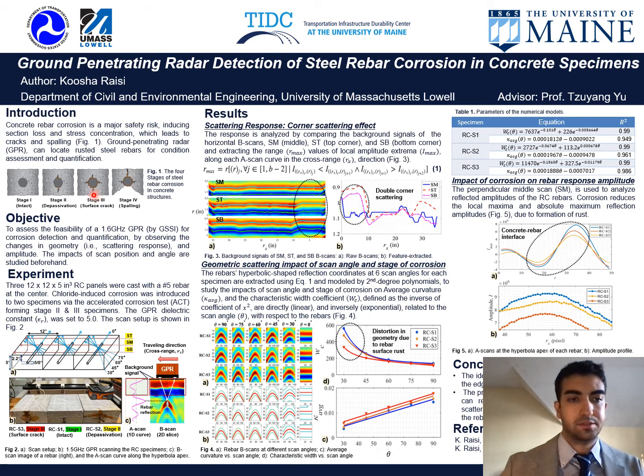And we have initiation of cracks, and at stage 3, the cracks have advanced to the surface, so we can basically see the cracks. And the last stage, which is the spalling, we can see that the concrete specimen or infrastructure is opened, and we can see the reinforcement. We call that spalling. And the specimen is hopeless and helpless at that stage.